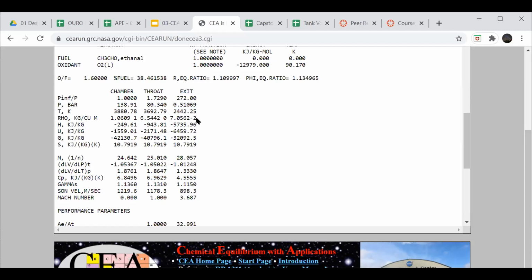Yeah, something like that. The other reason is, the lower your exit pressure, and we'll get to it later, the larger the exit area of the nozzle is going to try to be, and also the longer the nozzle. If you're in atmosphere, suddenly you have to deal with this massive nozzle, drag from the atmosphere on it, plus the weight. So you really want it to be somewhere around halfway through the burn on that engine for an actual launch vehicle.